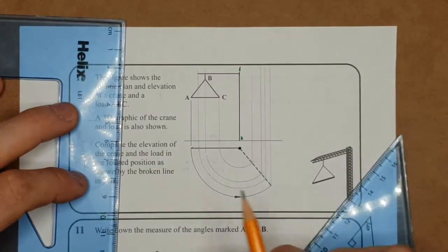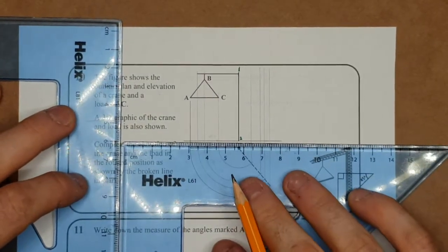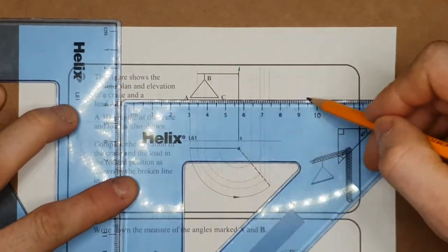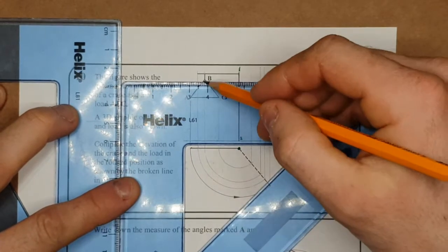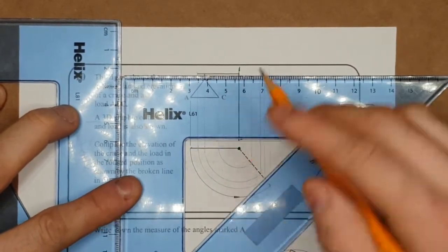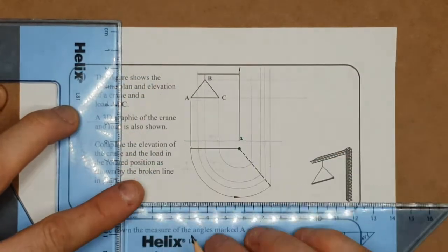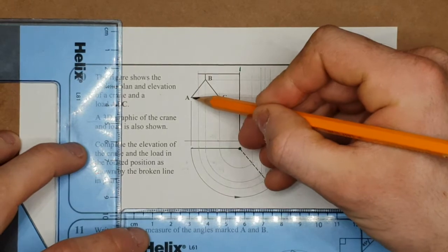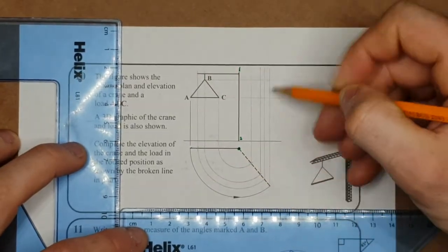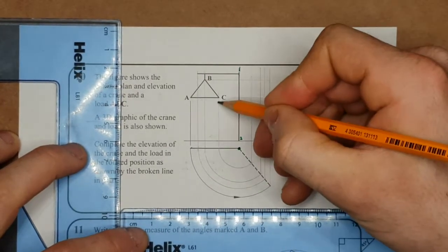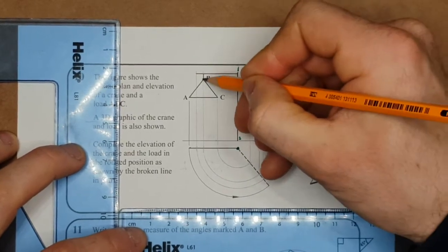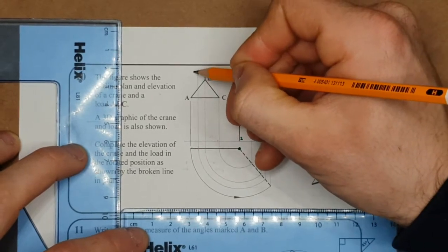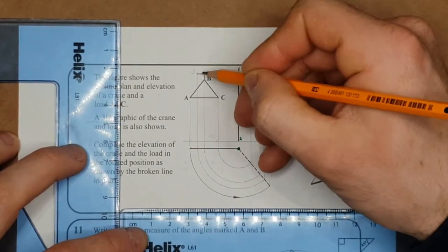Next, I'm going to bring them across, and just remember the simple little rule that heights don't change. So as an object pivots about, it does not change in height. Now, point A, if I just label now before I go any further while I'm set up with my set squares, point A is the furthest away. Point C is the nearest. Point B is this one here. And if I just call that point 3 there, so I have 1, 2 and 3.